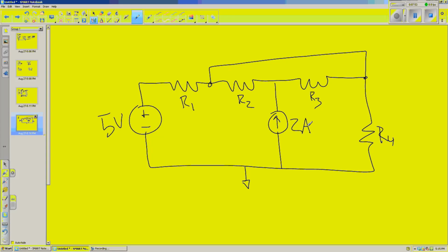And now, where are our nodes? Well, generally nodes are where we expect voltage to be different. So here we've got a node. We'll say this one is V1. We've got a resistor between those two points. So we know that some of that voltage is going to get dissipated as heat energy. We have one right here. Again, we have a resistor in between those two.